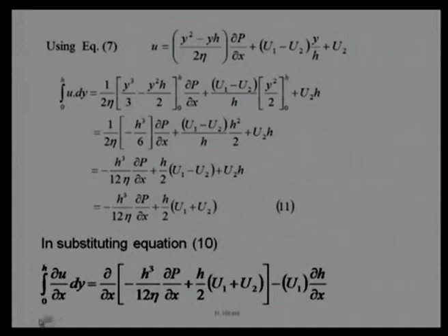We substitute here in the equation, and what we get is differentiation, and this is the same term minus u1 times the pressure wedge term, or we say the gradient of thickness. Now, we can differentiate, as we know dp by dx depends on x.